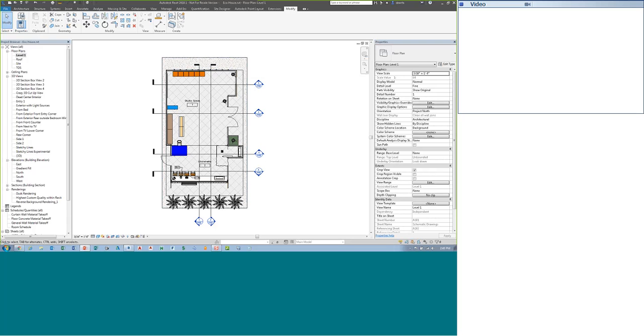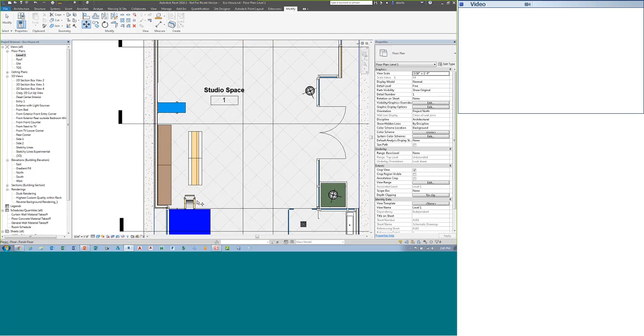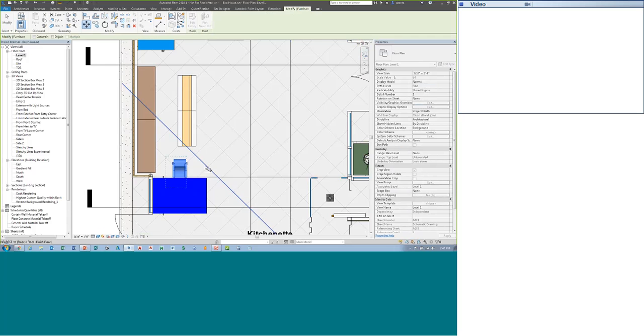The second command, the move command. So how do we use the move command? The move command, like all of the other modification type commands, is located in the Modify tab of the ribbon, Modify panel, and the move command is here. Most people will start the command and then select an entity, hit Enter, and then they'll move it from one location to another.